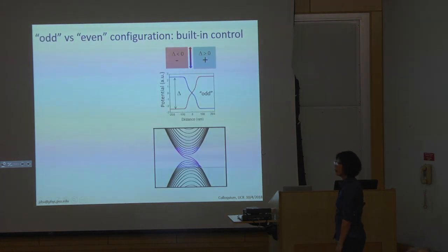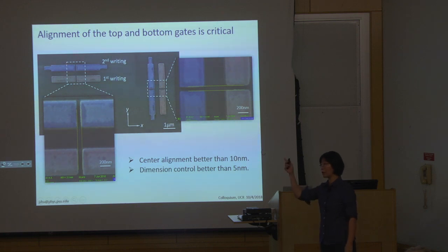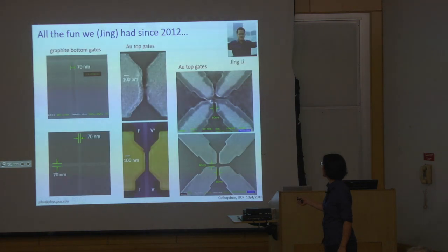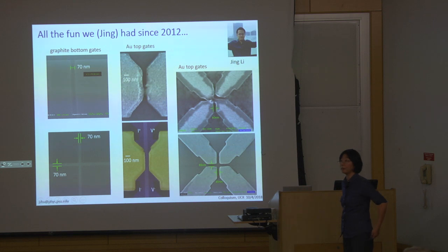Okay. The 70 nanometers, is that kind of the smallest you can get? So when you do a liftoff process, when you go below 50, the failure rate starts to go up. I'll show you a failure of the liftoff, which looks like that and looks like that. So the smaller you make it, the more challenging it is. You can do better with etching.